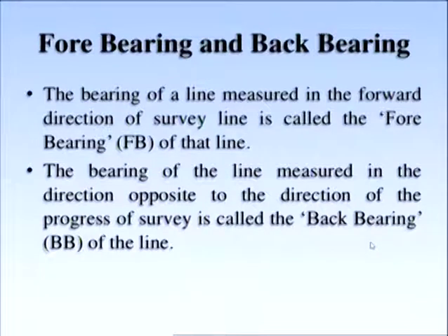Now, fore bearing and back bearing. What is fore bearing and back bearing? What is meant by bearing? Bearing is nothing but the horizontal angle which we take with reference to a line, in a clockwise direction.